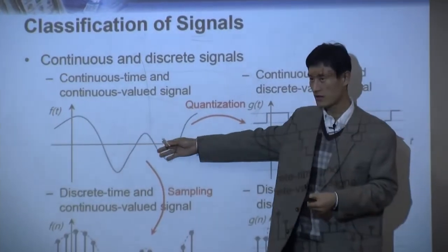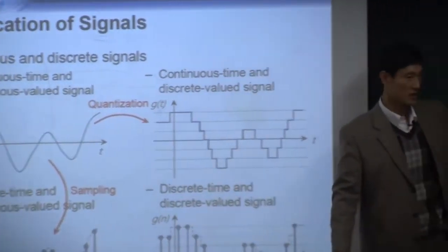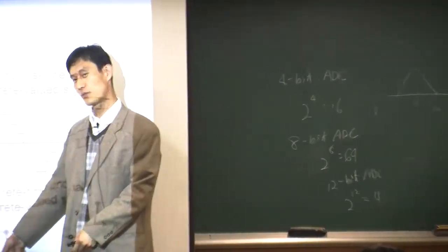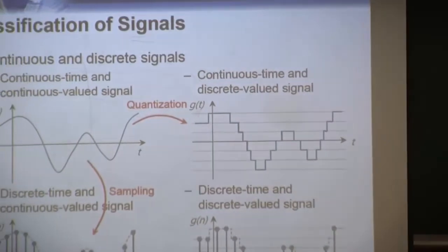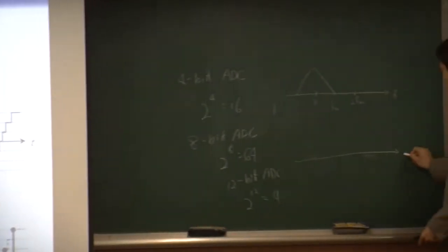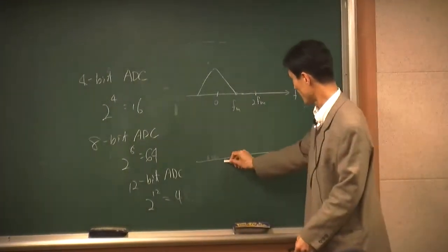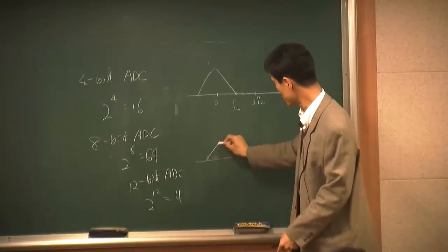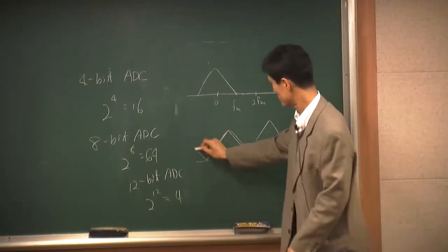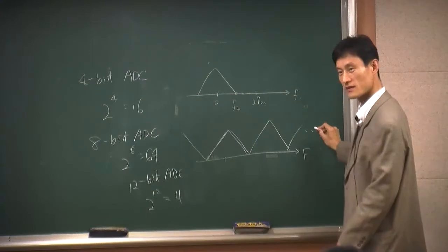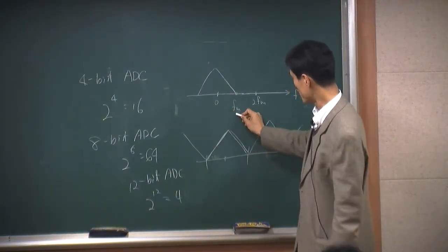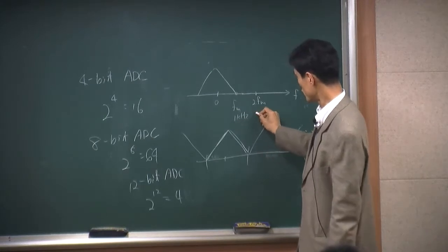So this is the analog signal. So you're going to look at this kind of frequency domain. Now you do a sampling and go to the digital domain. Okay, then our frequency domain now is going to be changed. And when you do sampling, that basically means that your signal basically repeats. Something like that, repeats, right? That's the digital. And from here to here, maybe here is FM, like 1 kilohertz or 2 kilohertz, something like that, right?